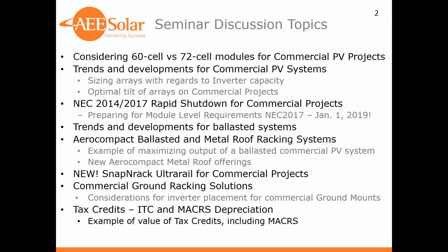We're seeing 60 cell versus 72 cell modules and considerations for which ones to choose for your commercial PV projects going through the rest of the year. We're going to talk about trends and developments for commercial PV systems and sizing of the inverters, and also considering the optimal tilt of arrays on commercial projects.